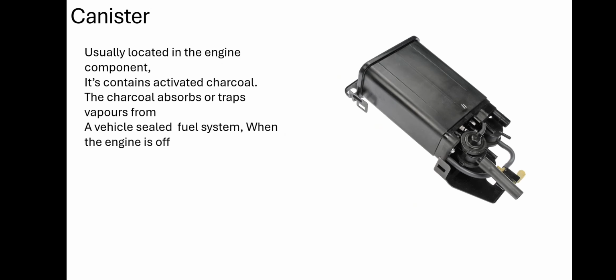Here we have the canister, usually located in the engine compartment. It contains activated charcoal. The charcoal absorbs or traps vapors from the vehicle's sealed fuel system when the engine is off.